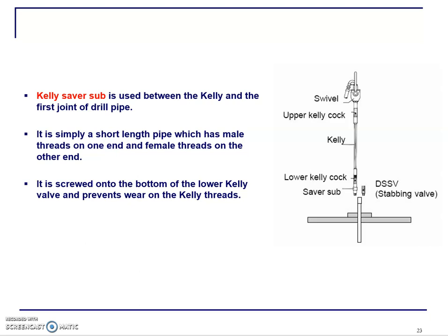So the reason that we use the Kelly saver sub is because it prevents wear on the Kelly threads, right? Because the Kelly is connected.